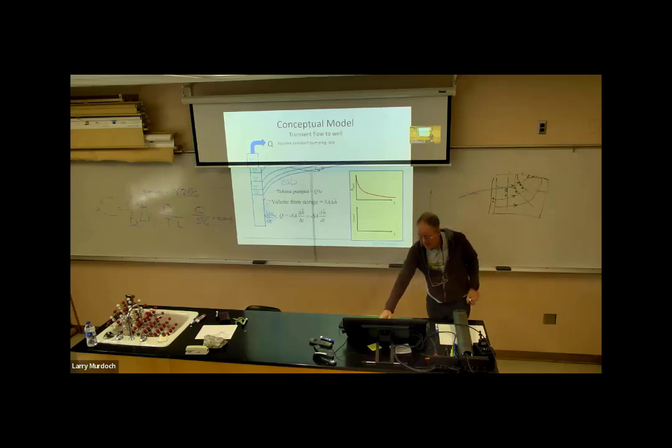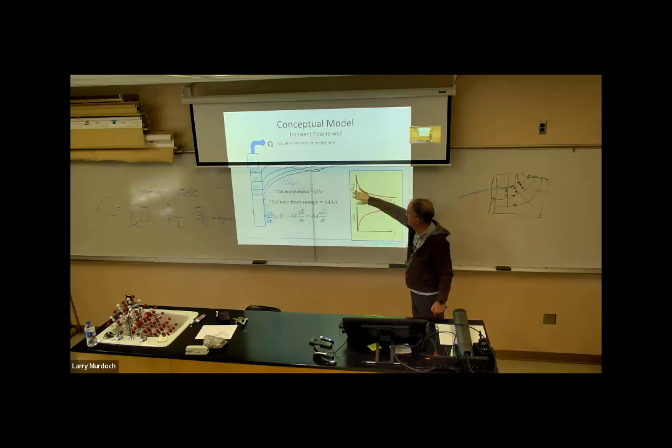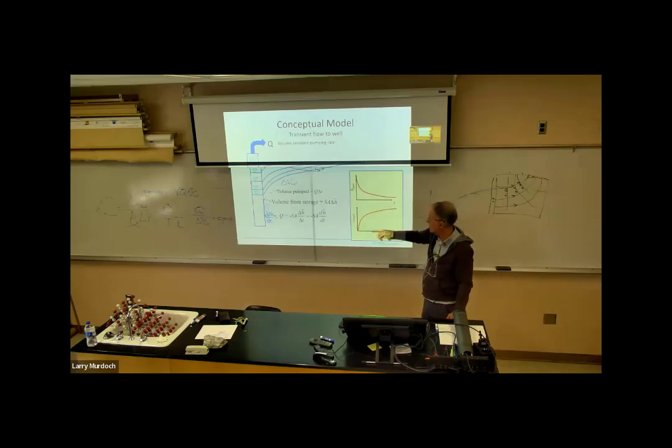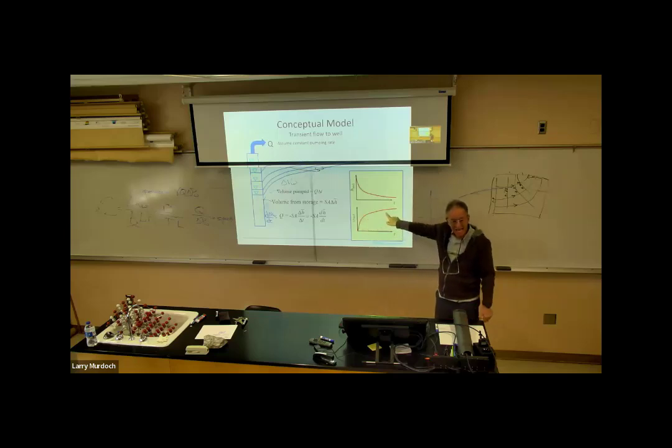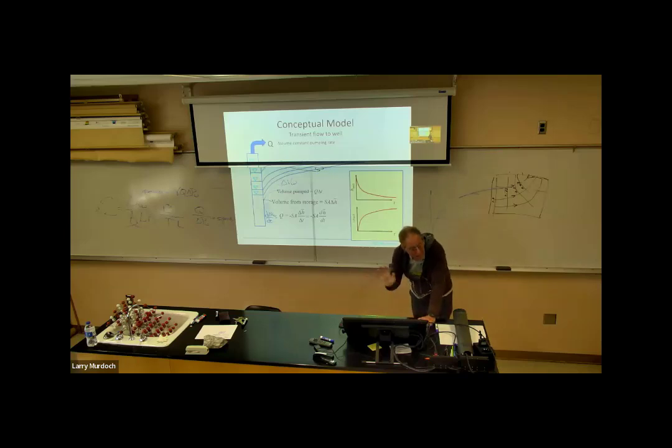Okay. So the drawdown then, this is going negative. The head is dropping, but then the drawdown is the flip side, or change the sign. So it's just the same function, but it's flipped like that. The drawdown is increasing. So the drawdown curve as a function of time looks like that. That's what we're expecting. We haven't done any analysis yet, but that's qualitatively what we expect this to look like.